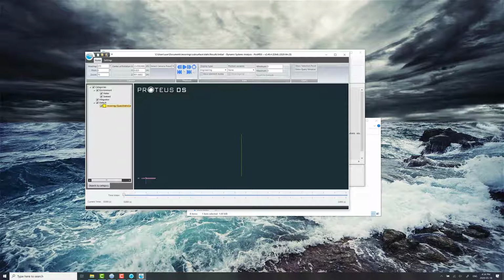And now we'll see what the mooring looks like deflected in the current profile that we set. So you can see there's the top of the water depth. Remember, we're in 1,000 meters water depth and only 100 meter long mooring, but we had quite a strong current and we've got some deflection there.